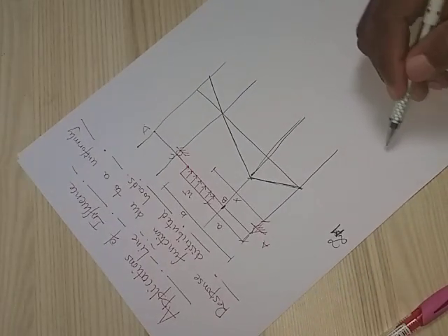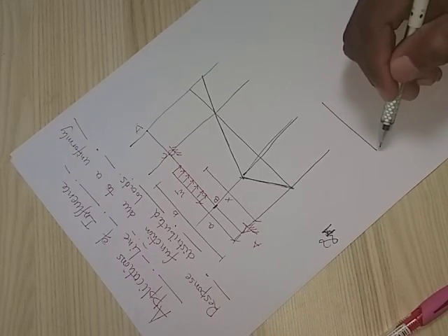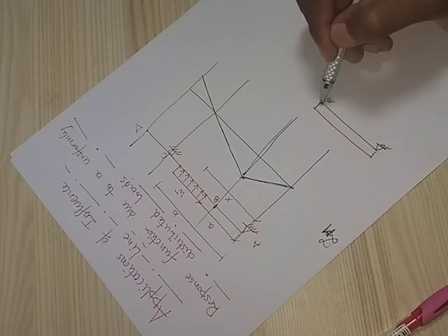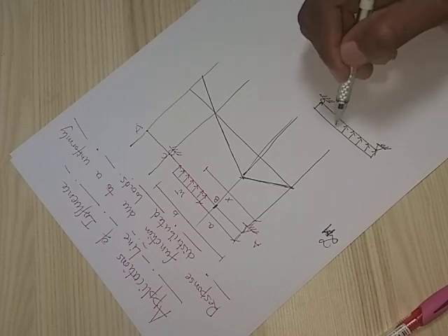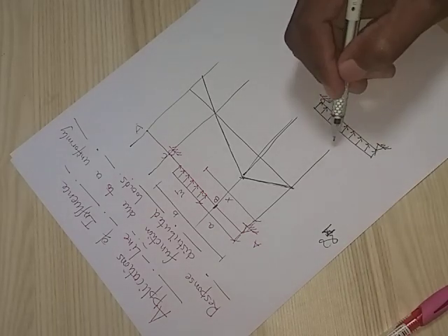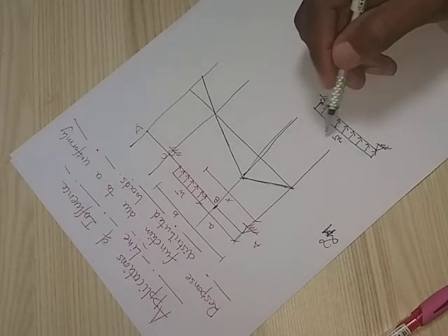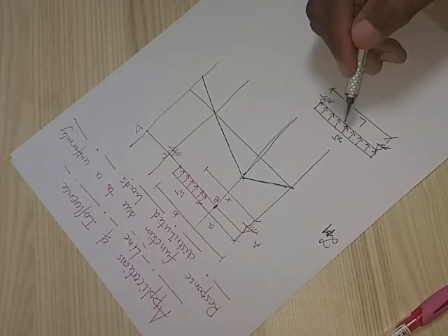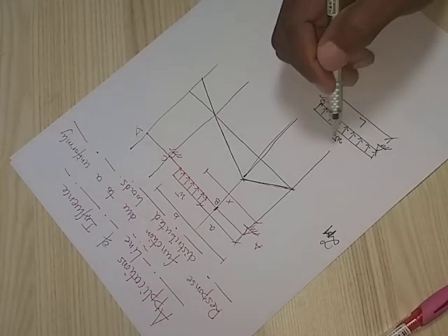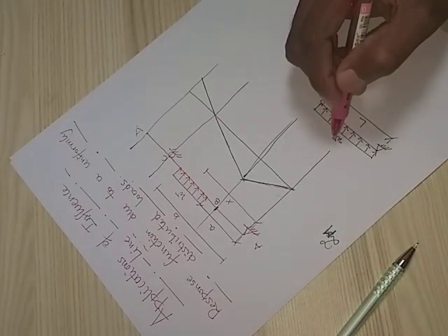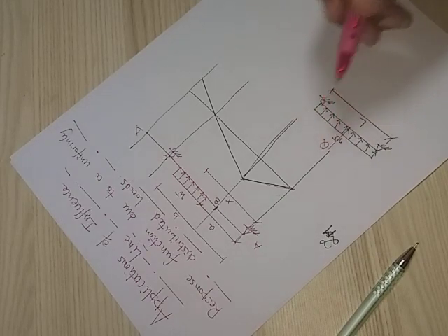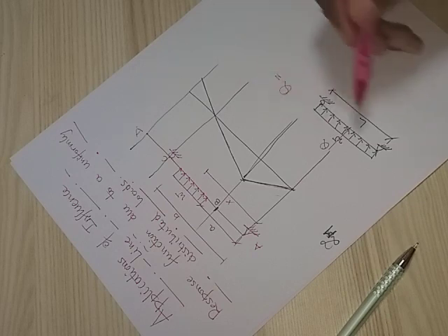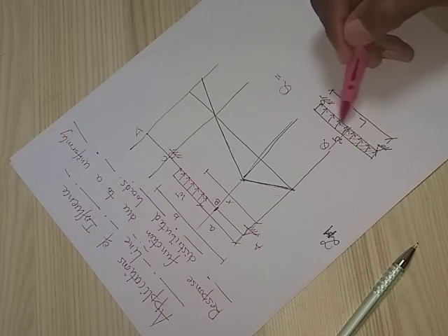Okay, let's make a review. We know that for a simple supported beam like this, when you have a distributed load with the intensity called W applied over the total length of the beam L, to find the equivalent concentrated load due to this distributed load, we call it capital Q. This concentrated load is the same as the area under the distributed load.